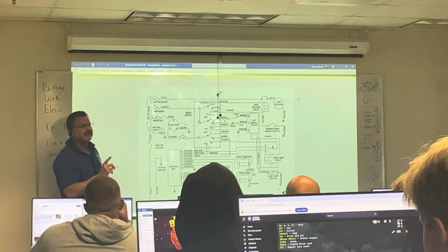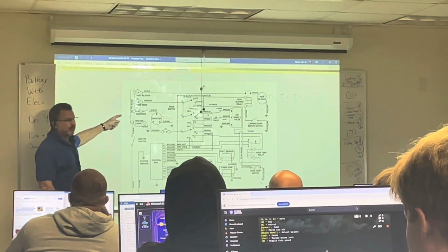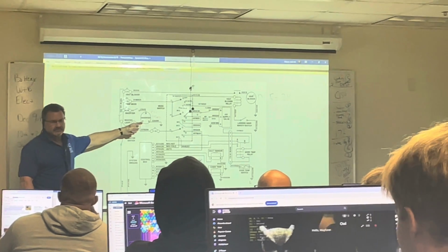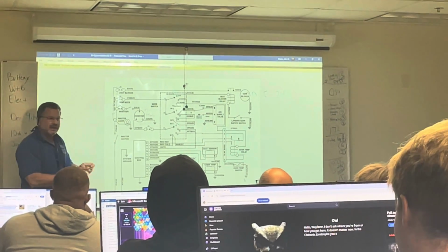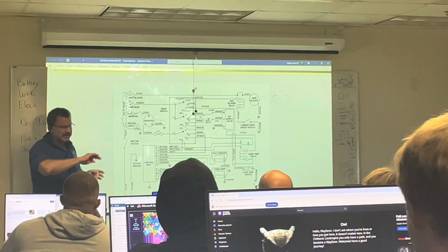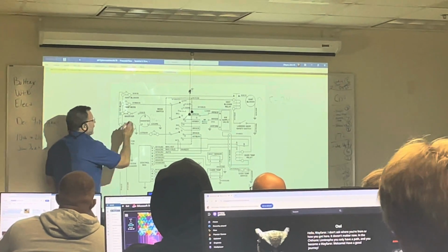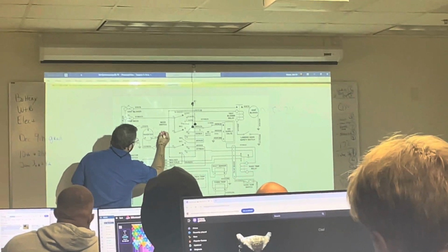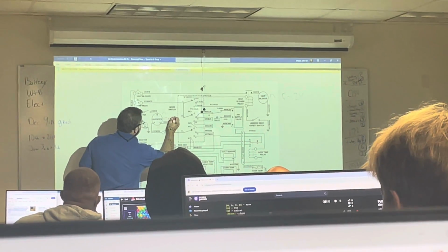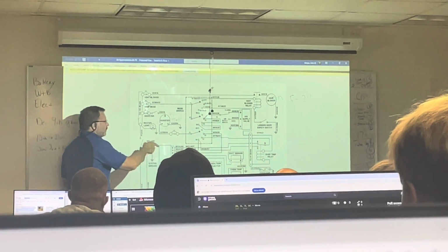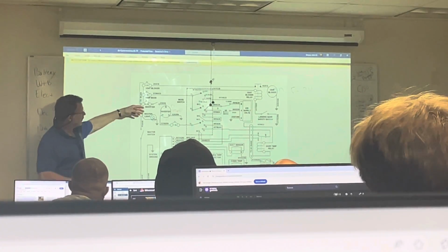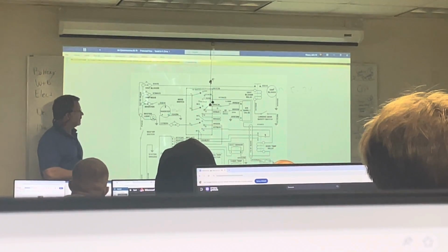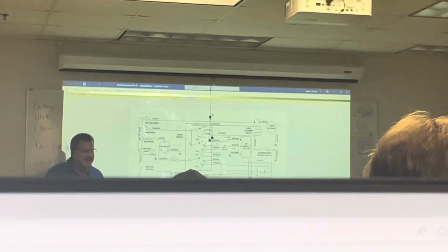27 or 28. If I'm only coming in with 24, can I get 115 going out? No, you can't. You have to have what it says to input to give you an output. So you will find that you're coming in with 24 and you're going to be going out around 110, okay? That will be your output because you're much lower coming in than what the inverter was designed to handle. We understand that, right? We can agree with that, right?